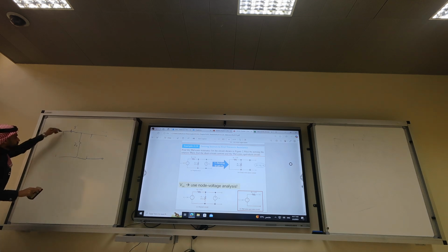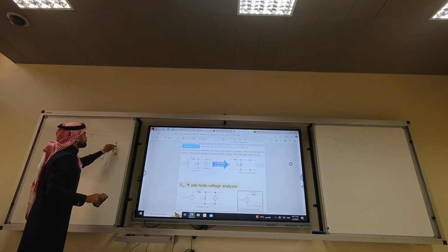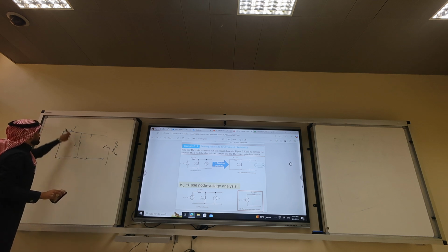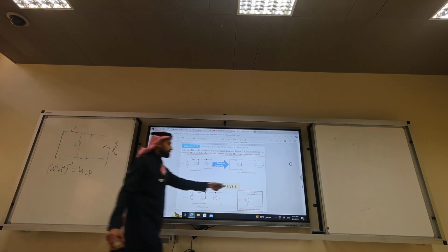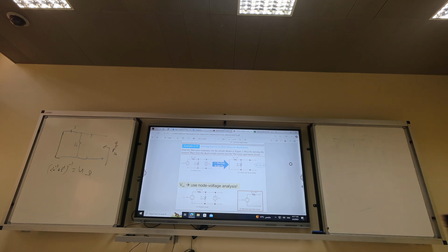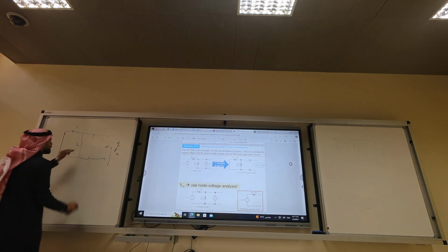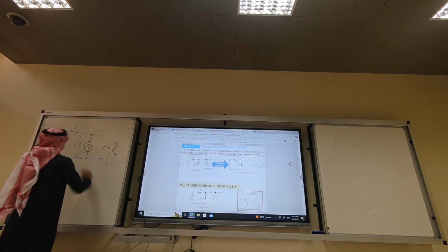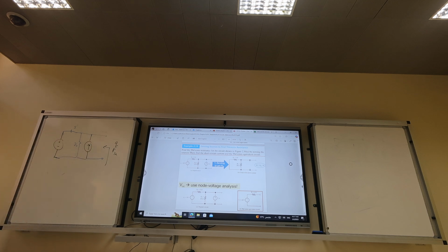How about the voltage source? Short circuit. And our Thevenin will look this way. So what he's seeing is 20 in parallel with 5, right? So what is 20 inverse plus 5 inverse, all inverse? 4. Get it? This is easy in the test. Thevenin would now do the harder task, which is finding V open circuit. He would put back the current source. He would put back the voltage source. And he would look that way.